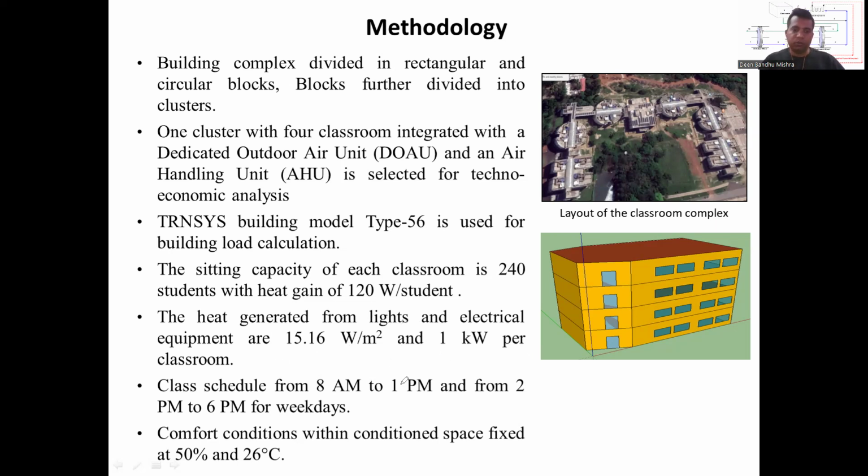The class is scheduled from morning 8 a.m. to 1 p.m., with a lunch break from 1 to 2 p.m., and again from 2 p.m. to 6 p.m., from Monday to Friday. There are no classes scheduled on the weekend, Saturday and Sunday. And the comfort condition inside the class is fixed at 26 degree dry bulb temperature and 50 percent relative humidity for calculation of building load.